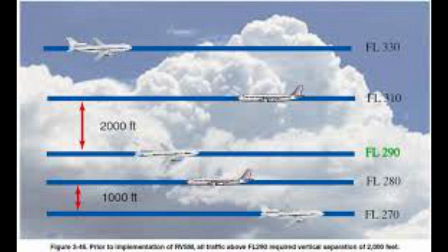Over time, air data computers, ADCs, combined with altimeters, have become more accurate and autopilots more adept at maintaining a set level. Therefore, it became apparent that for many modern aircraft, the 2,000-foot separation was not required. It was, therefore, proposed by ICAO that this be reduced to 1,000 feet. Between 1997 and 2005, RVSM was implemented in all of Europe, North Africa, Southeast Asia, North America, South America, and over the North Atlantic, South Atlantic, and Pacific Oceans.